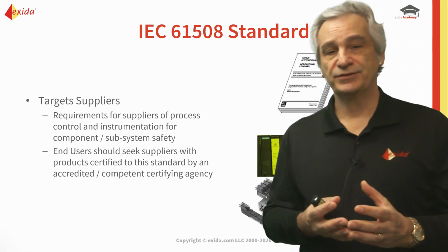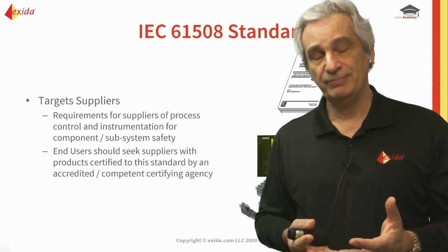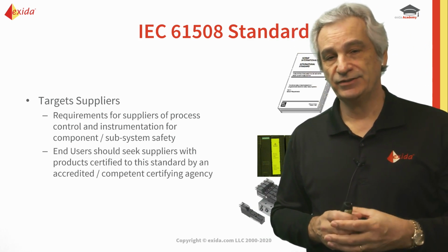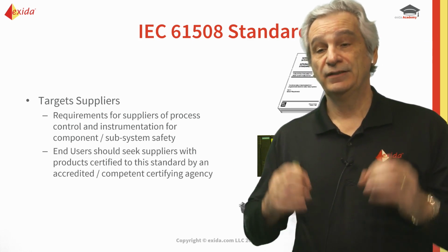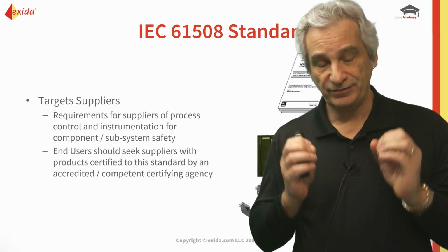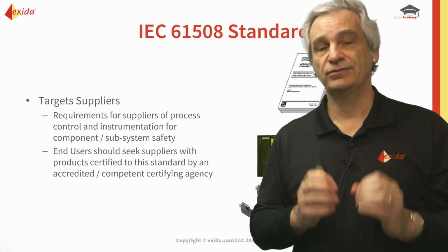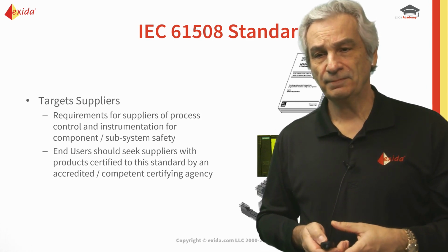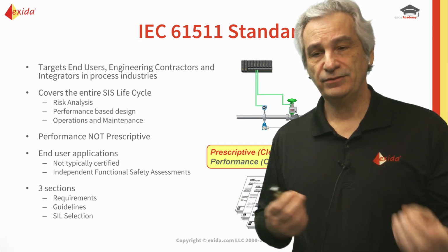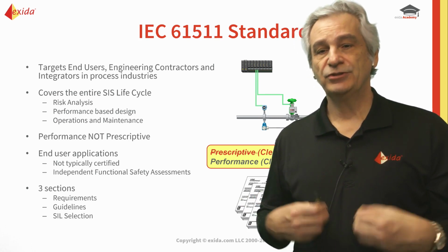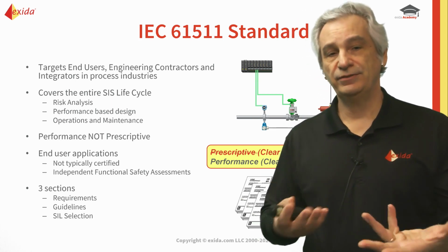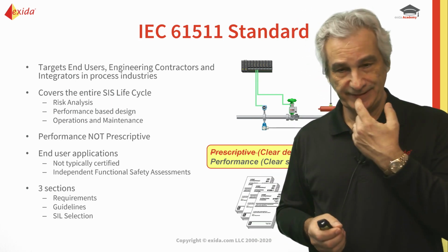And then again, of course, the higher the SIL claim, the much more stringent the investigation has to be to prove that we've not introduced any potential systematic faults. From the end user's point of view, we should be using devices that have been certified, but for end users, typically we don't certify the end users.